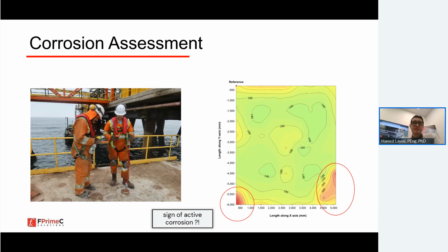But why did we do this? Those cracks you saw in the first image were at the soffit area. We wanted to evaluate from the top because it was easier and more cost effective. We wanted to see that if the condition at the top is bad, then the condition at the bottom is generally very bad. So that was the overall methodology for this assessment.